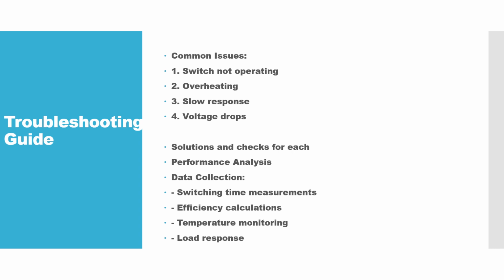Now the common issue is the switch not operating, commonly due to the soldering process of the switches. Even most of the torque switches, when you are soldering and you are not using the soldering iron properly or in the right manner, damage them easily.